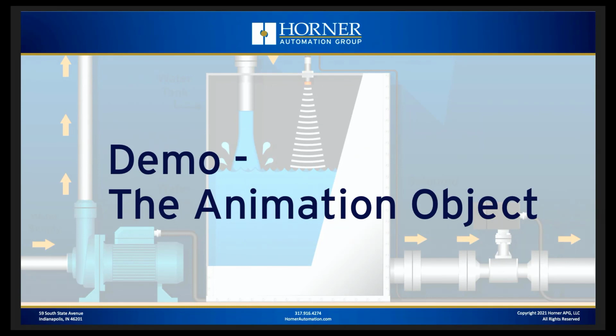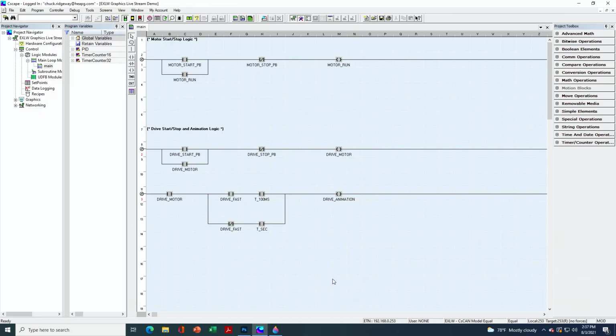Okay, now let's take a look in Cscape how we're going to make this guy work. All right, so back we go to Cscape. And what I have here from a logic standpoint, if we take a quick look at that here, the first thing we're going to do for my motor is let's just make the motor change its appearance when the motor's actually running. So let's use animation for that. All right, so this is just a simple start-stop circuit that controls my motor running.